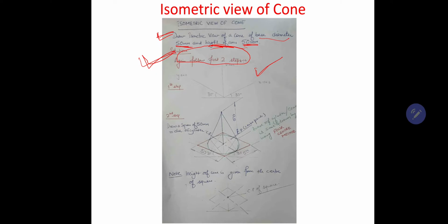I do not need to repeat the same points, because you already know what the four center method is. In the four center method, what we generally do is mark points at the center of each line, then we join these lines, which forms a shape of a star, or you can say a spider. Then we draw four arcs by taking four different center points, and then we get the base of a cone.